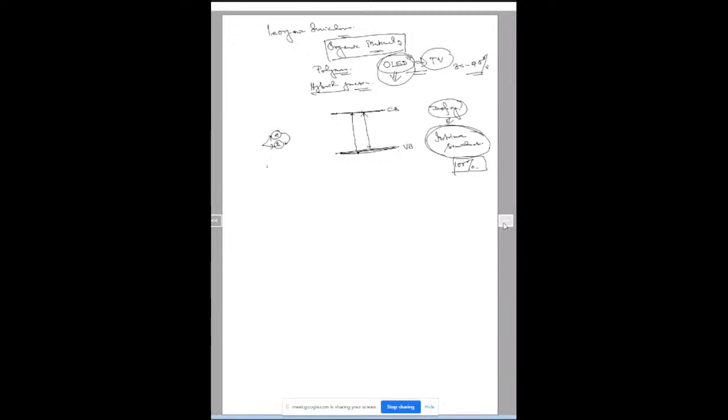Right. So we say that the concentration of electrons, denoted by n, and the concentration of holes in the semiconductor will be the same. An intrinsic material is one in which the number of electrons is equal to the number of holes. All these numbers of electrons and holes are measured per unit volume. In MKS units, we denote it per meter cube. In silicon, for example, this concentration is 1.5 into 10 to the power 16 per meter cube. This is the number of electrons and holes we generally find in silicon at room temperature,